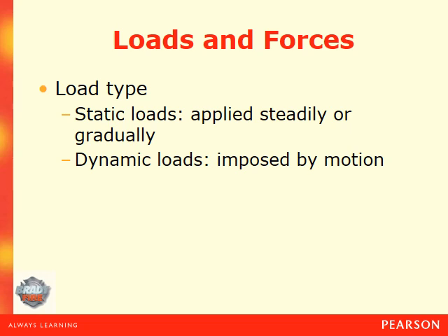Now, when we're talking about loads, you have things known as static loads and dynamic loads. Static loads are applied steadily over a gradual period, and dynamic loads are imposed by motion or something that shocks a building. A good example would be dumping 10,000 gallons all at once on a roof, where a static load could be like rain for 2 days straight, where the water's slowly building up on a flat roof, leading to collapse.